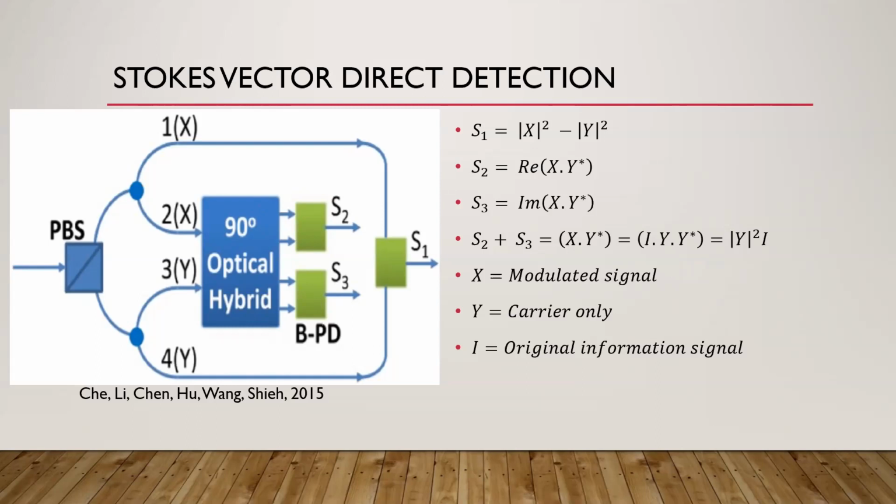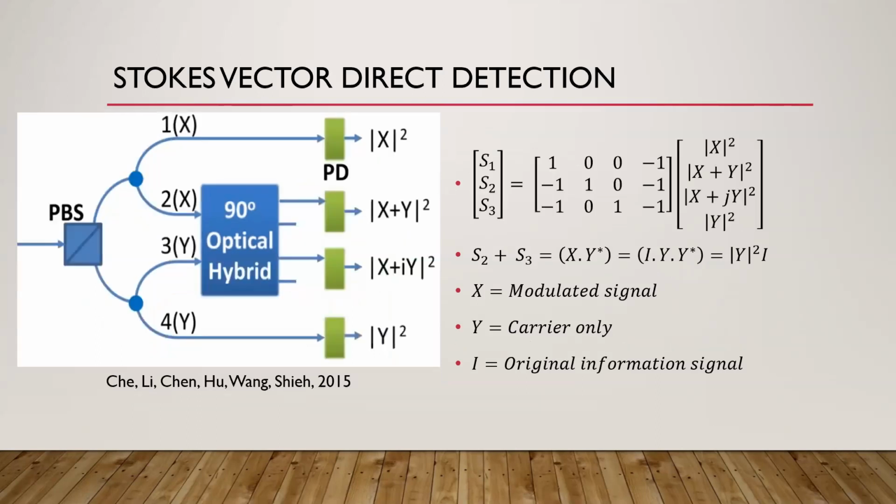There's lots of different circuits that we can use. So this one here is just an alternate one. These were all taken, as the slides say, by the way, from a paper by the names mentioned there. So there's lots of different ways of combining it. This particular version uses an optical hybrid, and then instead of balanced photodetectors, just photodiodes. And it means that the outputs that we get from the photodiodes are not exactly what we're looking for. So we need to multiply them by a fairly straightforward transfer function.